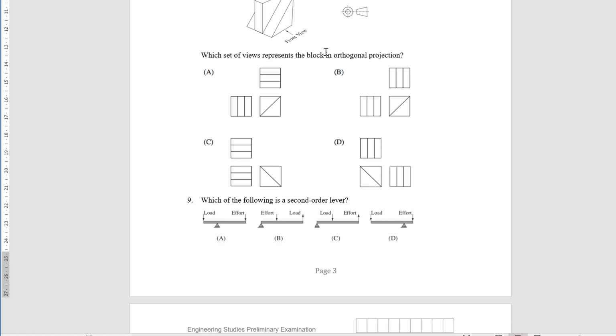Okay, in this picture, I've talked about this recently, so I'm not going to harp on it. We're looking at the front view. It looks like a sandwich, so it's going to be this triangle. When we're looking from the direction of that arrow, we're going to see this line here in the top corner and this in the bottom corner, so it's going to be either A or B. And then as we go further back into the page, we're going to have a line that is parallel to the viewing plane. Now, Copeland likes to refer to this as perpendicular to the axis of the view. I like to think of it in terms of being perpendicular to the piece of glass in front of the camera. So A is the short answer.